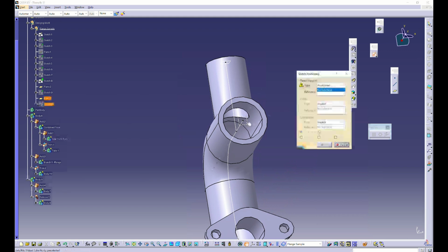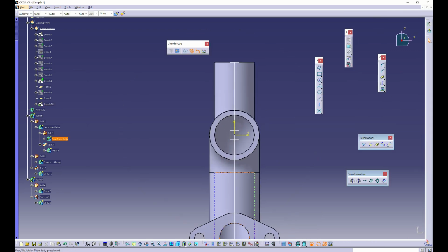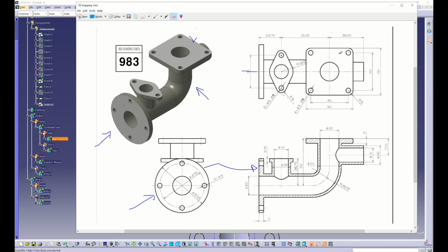Then create a sketch, the same. So project a point for the origin. We have it rectangular, so 50 by 50. Then the hole is 40 by 40, no? The distance of the center of each hole. So yep, it's a quick one.